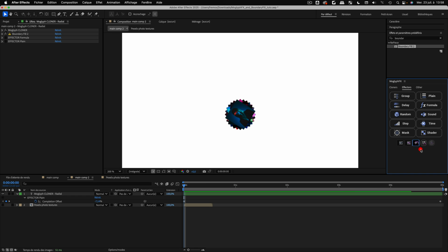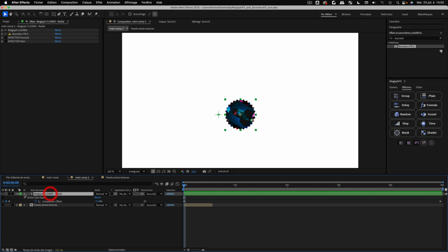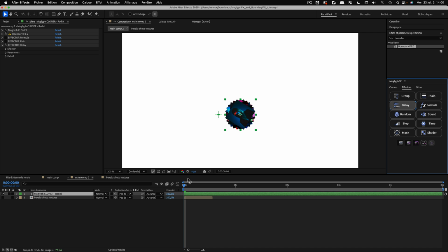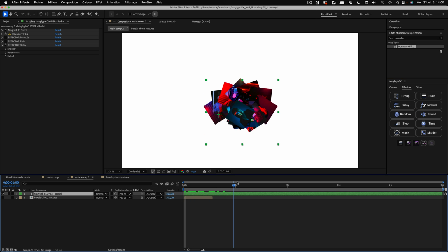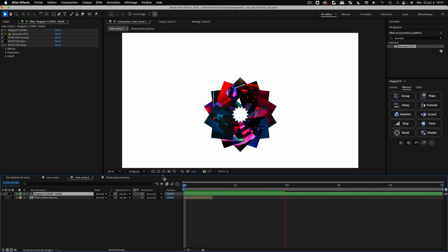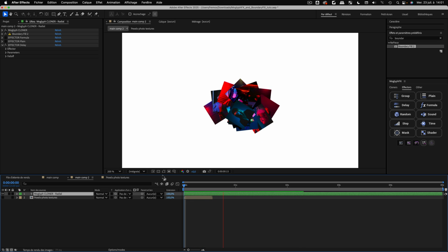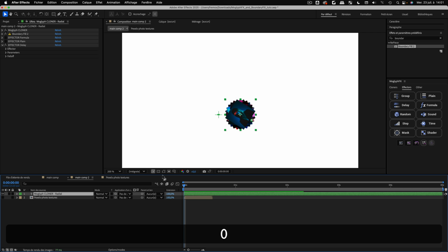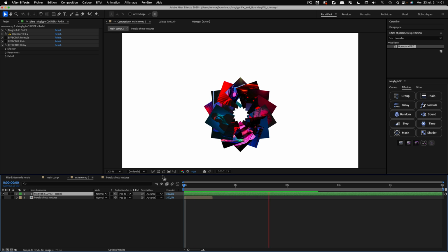So I will change from square falloff, which is default, and I will select my MoGraph Cloner radial layer again and click on Delay effector. Once you click on this button, it will animate each clone one by one with a really nice springy motion, and I really love this one. Look at this, really, really cool.